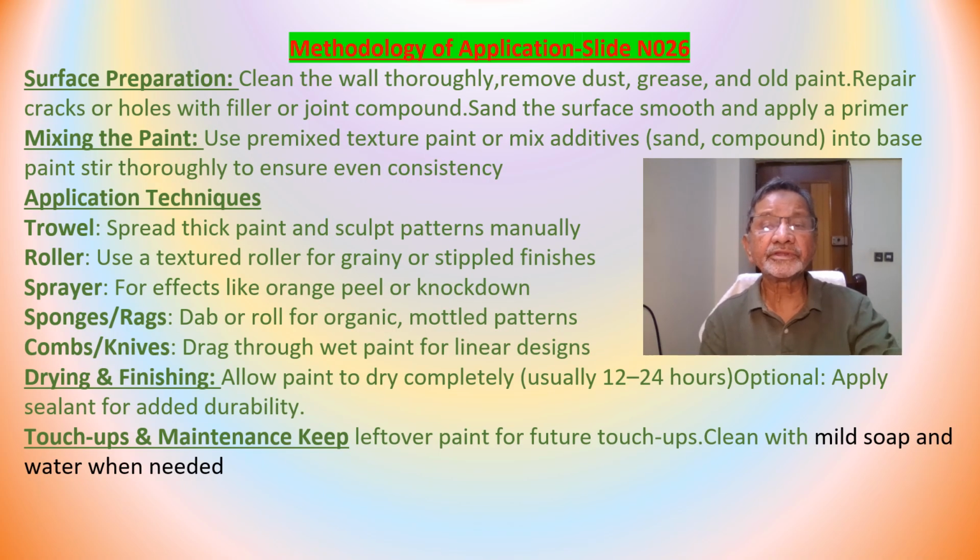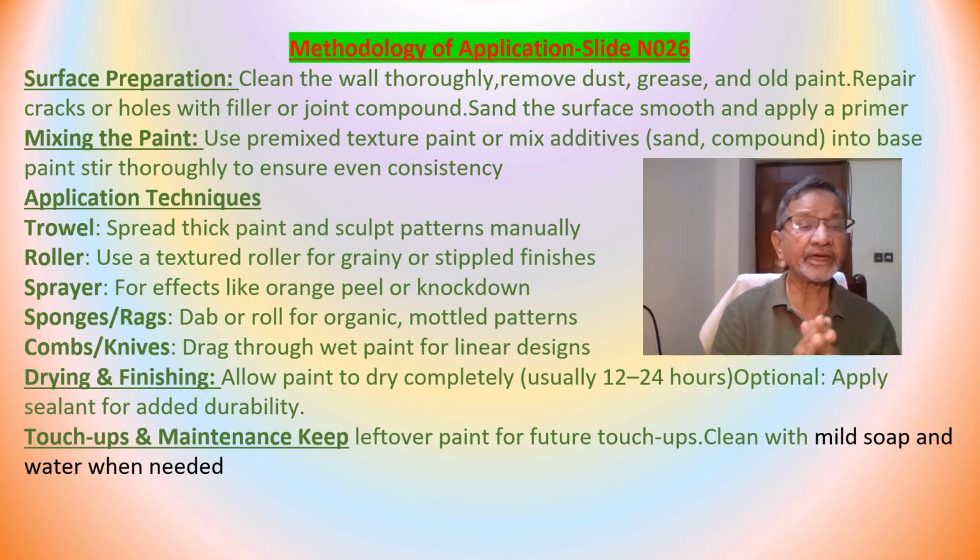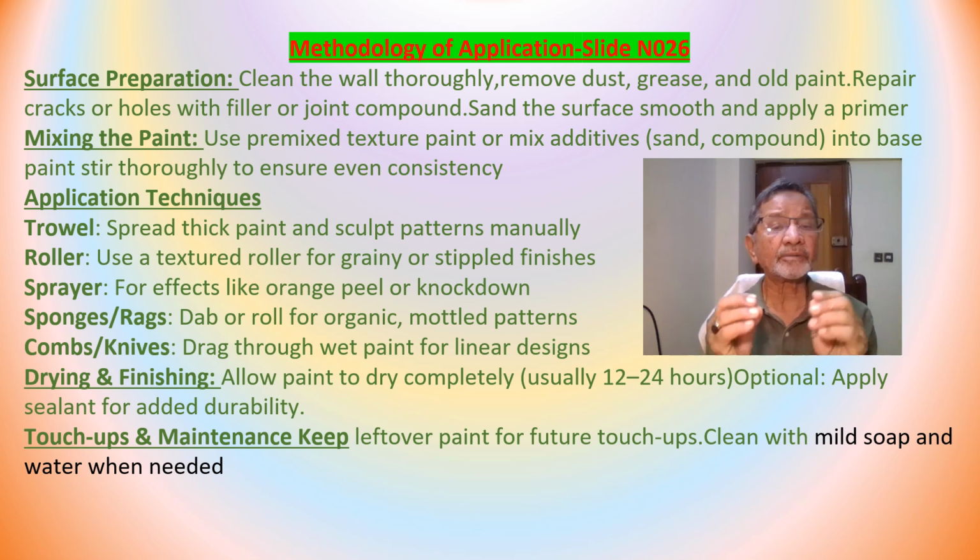Dear viewers, in this slide number 26, we are going to discuss the methodology of texture paint. To start, we have to prepare the wall, clean it, and remove the debris and dust particles. Holes also have to be patched.